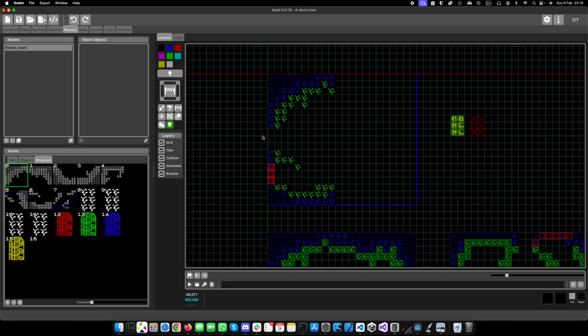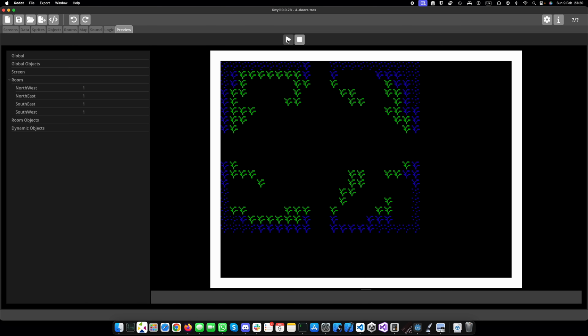So if we go quickly to the map, we'll drop one into place anywhere on the map, it doesn't matter. And you can see if we go to the properties, we have these 4 variables. So if they're all set to 0 to begin with, it should use the first variation, and that's what we get, the first variation. So let's just check that this is working by changing them all to the second variation, and we should get the alcove versions of the brushes.